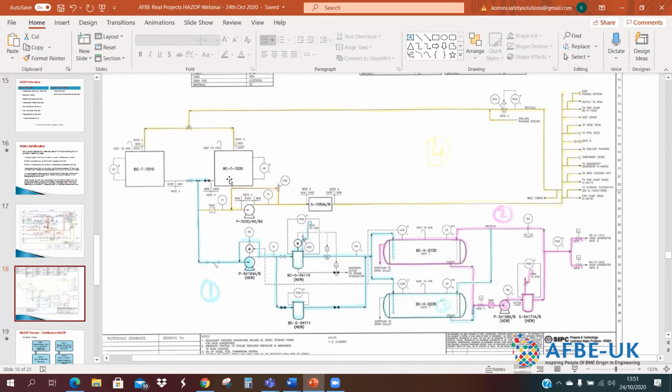So first off, your raw diesel system, the yellow lines there, the yellow bits on that P&ID, are being taken as one node, the supply and return to that raw diesel system. And then the blue bits here are the drain lines from the supply lines from the diesel system via the strainers to the auxiliary supply system. Those are being taken as two separate nodes. And you would see as well that the two diesel tanks, which are separators, are being treated as two separate nodes.